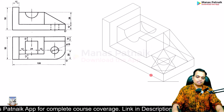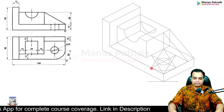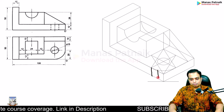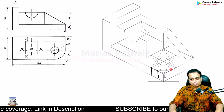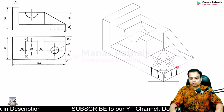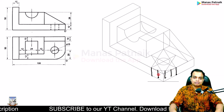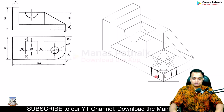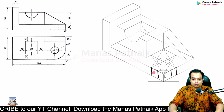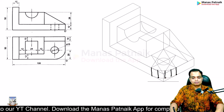Done. What about the quarter circle at the bottom? It is very easy. 12 mm below, make a point. Again 12 mm below, make a point. 12 mm below, make a point. And through all of these points, you don't need to make these lines. Okay, just mark these points. These points are going to act as guidelines for you to finally go ahead and make this curve like this.